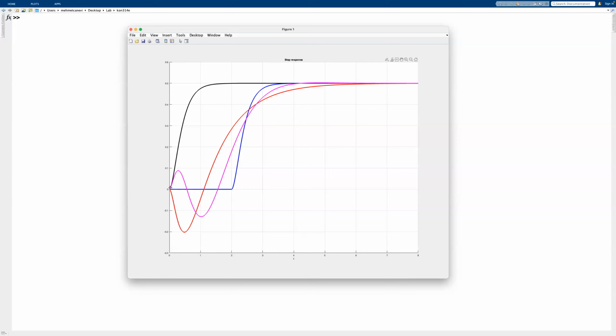Now, if you look at the magenta one, which is the second order approximation, then we go upwards now, up to 0.1, and then we return to 0. This is the first part where we wasted some time in terms of delay. And then we have undershoot, where we waste a little bit more time, and we reach 1.55.